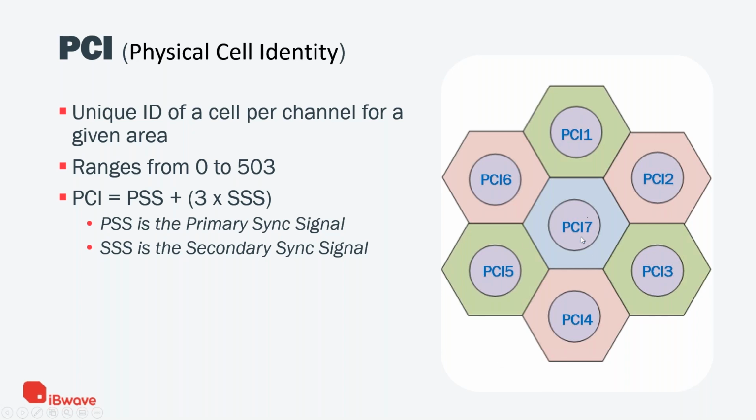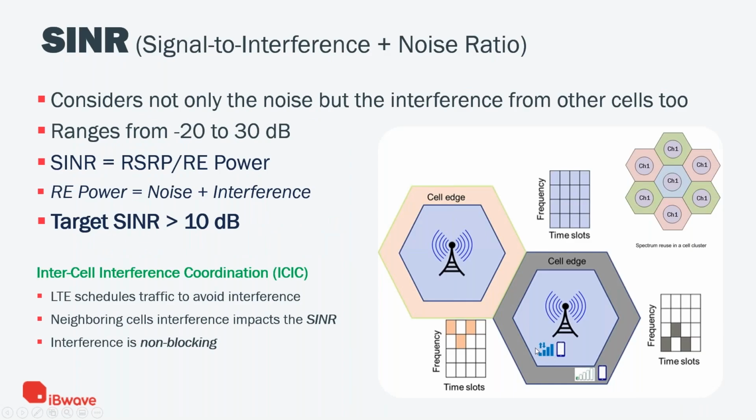At the center of the cell, you could use the entire resources, or all the resource blocks, ideally. And on the cell edge, you try to use roughly one third, or maybe 25%, because if they are all using the channel, you try to reduce the number of resource blocks used. So at the cell edge, not only do you get low coverage, like in this picture, closer to the cell you get really good coverage, like 4 or 5 bars, and at the cell edge you get very low coverage.